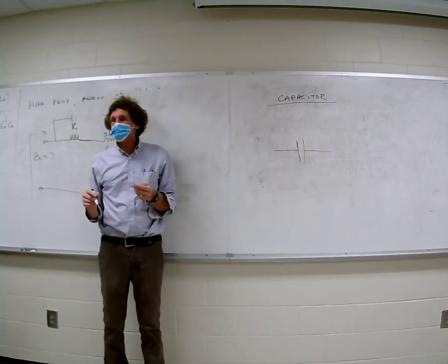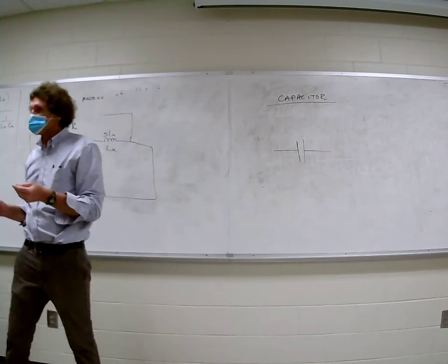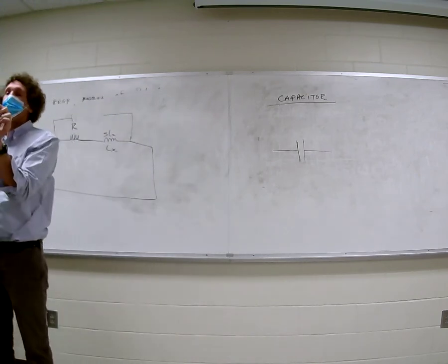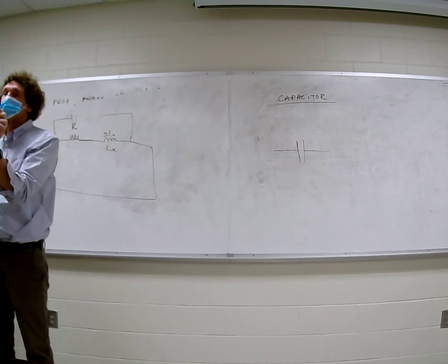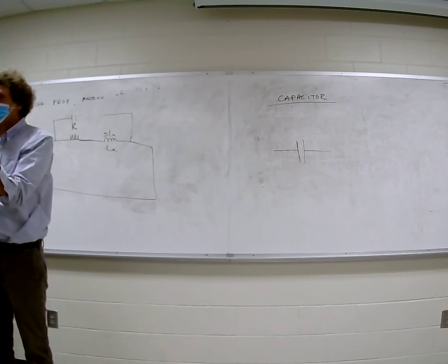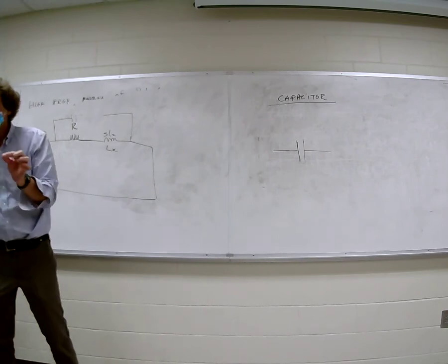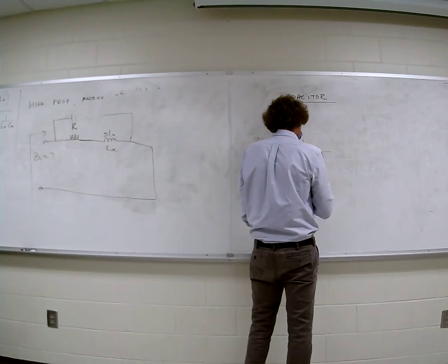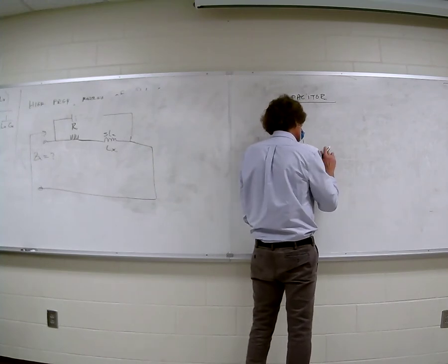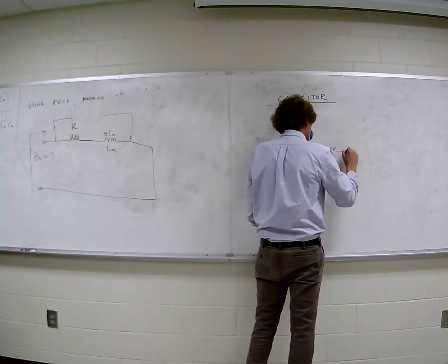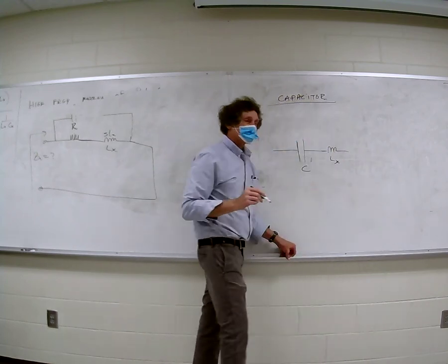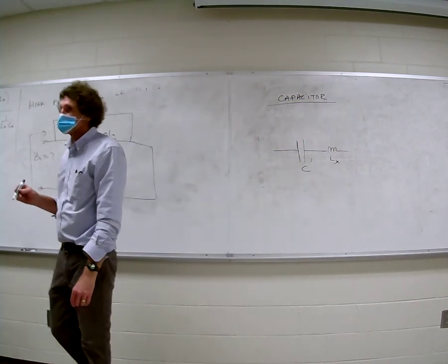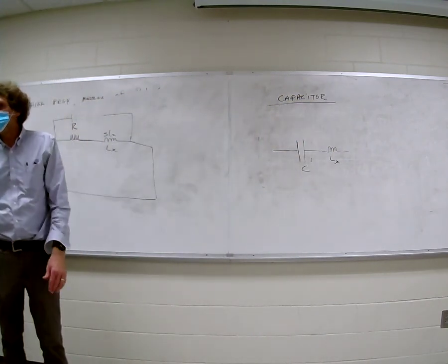Now, think always in terms of the components you're used to. You're used to small little capacitors, right, that have short leads, less than an inch on either side, correct? And you cut them down if need be, or bend them if you're doing breadboard. Well, anytime you have wire leads, you have inductance. This is C, we want C, but we get this unwanted L. And whenever we don't want something, we put a sub X. It's just the way it is.